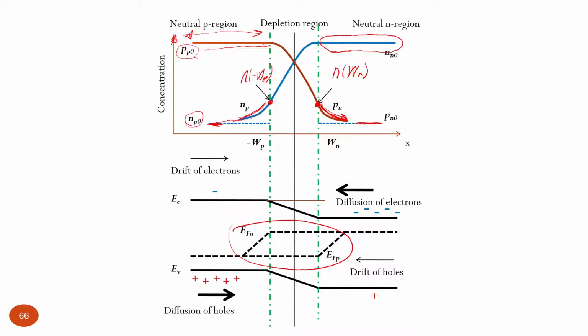As you remember, we had a similar procedure done when we considered diffusion of majority charge carriers in a p-n junction. You can recall this if you forgot. And there we derived the Maxwell relaxation time, how fast we can change the concentration of majority charge carriers, and also the Debye length, the distance along which the excessive concentration of majority charge carriers decays by a factor of e.